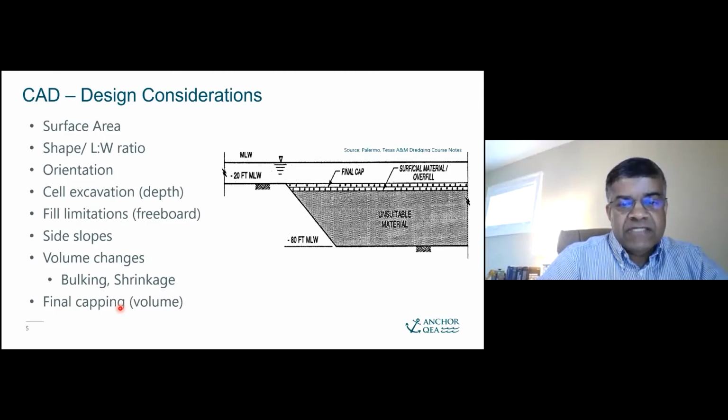And oftentimes the dredge fill cost is zero because it's coming from another dredging project and they bear the cost to transport. So all of that plays into this. The other factor related to the analysis we talked about earlier is the volume change. So when you disturb a dredge sediment from a channel, we're increasing the void ratio, we're bulking it, quote unquote, and typically you can gain anywhere from 25% to 40% increase in volume.